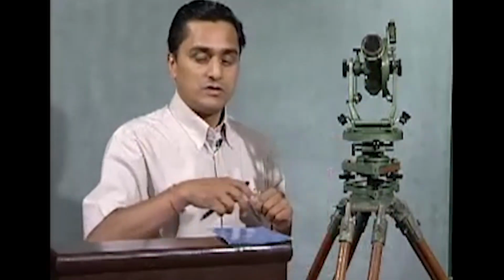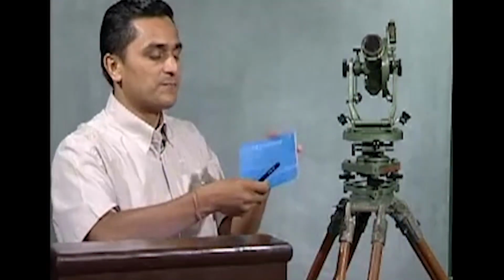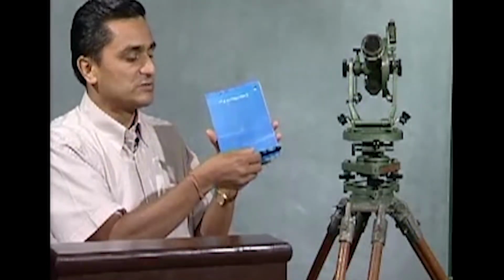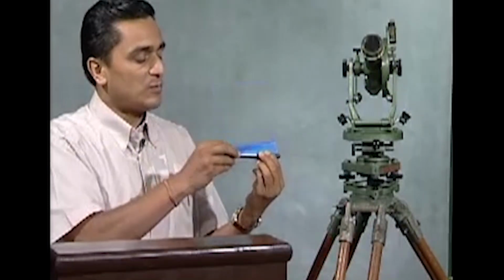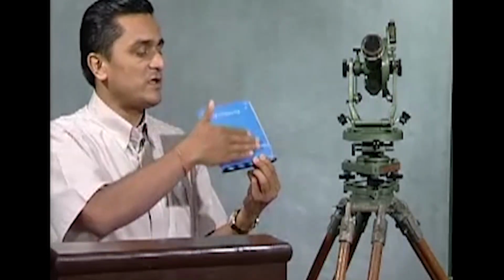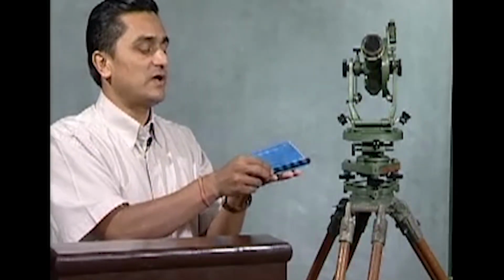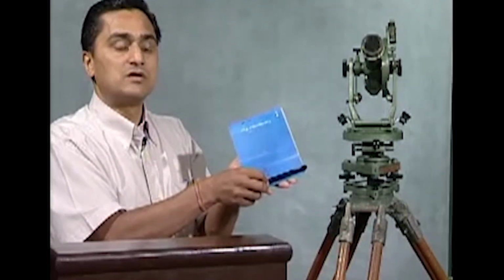Okay. Now there may be a case, for example, just think here. If this black pen is the bubble tube, right now the bubble tube is horizontal, but how about this plane? This plane is not horizontal. This plane will be horizontal only in this case. So there may be cases when the bubble tube is in center, but we are not sure whether the plate is horizontal or not.